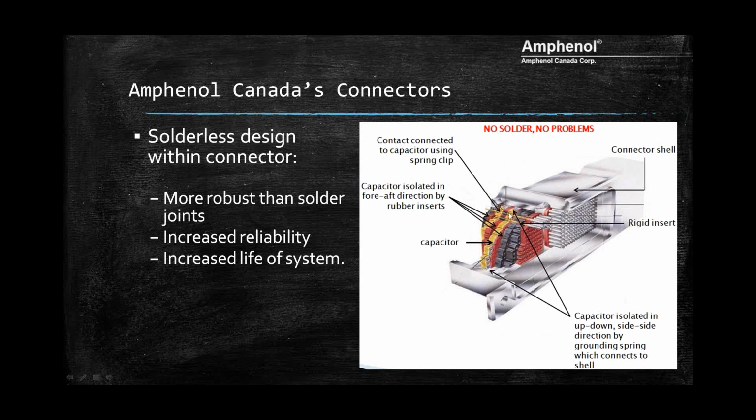The other thing that's important too is that the capacitor is isolated for shock and vibration because it is sandwiched between hard inserts using a rubber insert here. What this does is it provides support and protection, a shock absorber if you will, for the capacitor in the fore-aft direction.